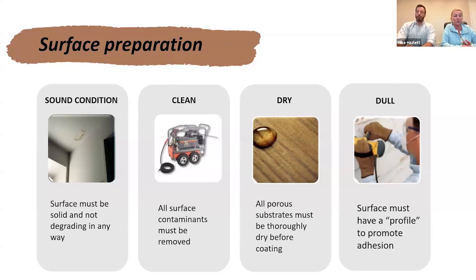Coating integrity and surface life can be reduced because of improperly prepared surfaces. So 80% is quite a big number to consider when we're talking about surface prep. And again, when evaluating the surface and the prep required, consider the condition it's in and answer these questions: how clean is it? How sound is it? How dry and how dull is it? We ask to address all 4. You can't really get away with 2 out of 4 or 3 out of 4.